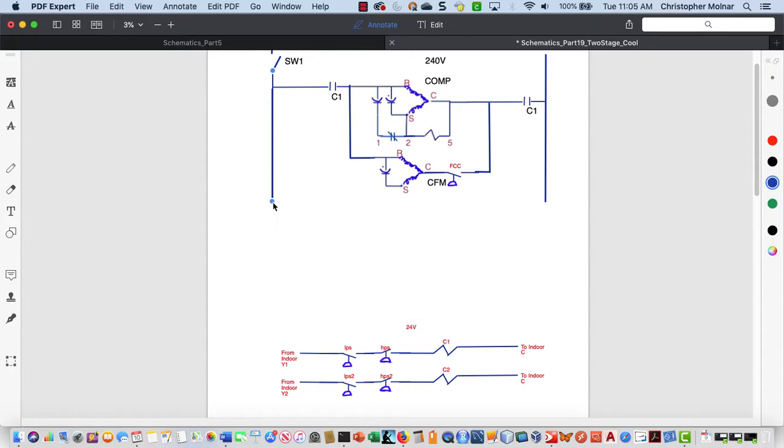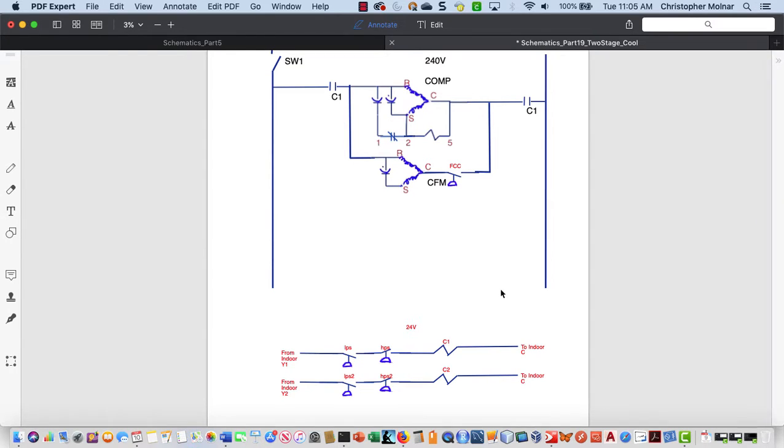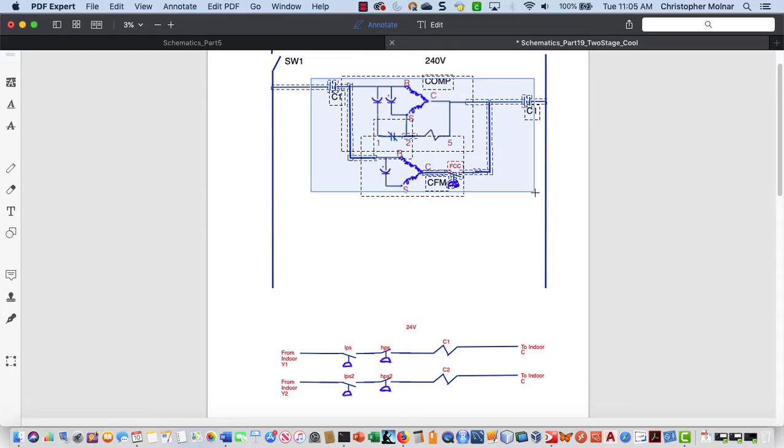We're going to deal with it first with a second compressor, because we can't have two complete refrigeration circuits that are independent of each other, or we can have a solenoid that closes when we have this situation going on. But most often on commercial equipment,